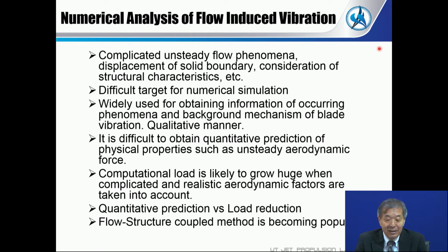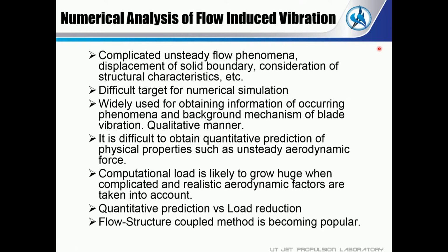But from the CFD side, flutter is a very difficult target, but it's widely used for obtaining the information of occurring phenomena and background mechanism of flutter vibration in a qualitative manner. But it's difficult to obtain the quantitative prediction of the physical properties, such as unsteady aerodynamic force.